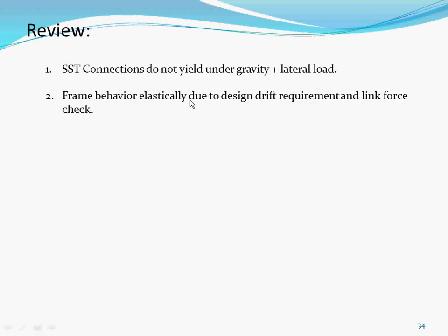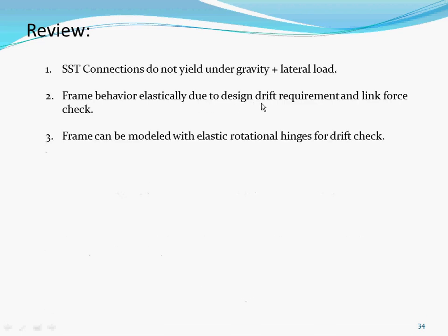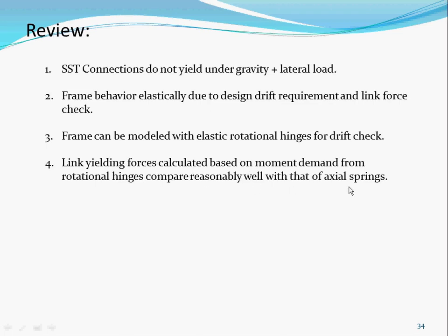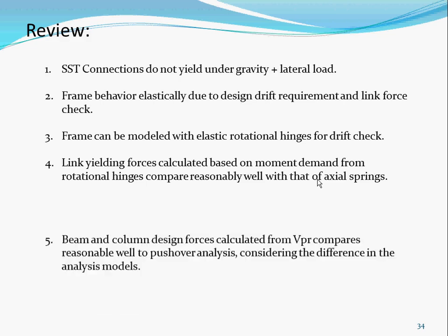The frame behaves elastically to design drift requirements or link force. Model with elastic, or the other one with the hinge for drift check. Link yielding force is calculated based on moment demand or from the spring. You can actually read it off the spring in SAP. That's one good thing: instead of having to calculate a moment divided by the depth, in SAP you could just read off what the spring axial forces are. So there are different models for how to do that.